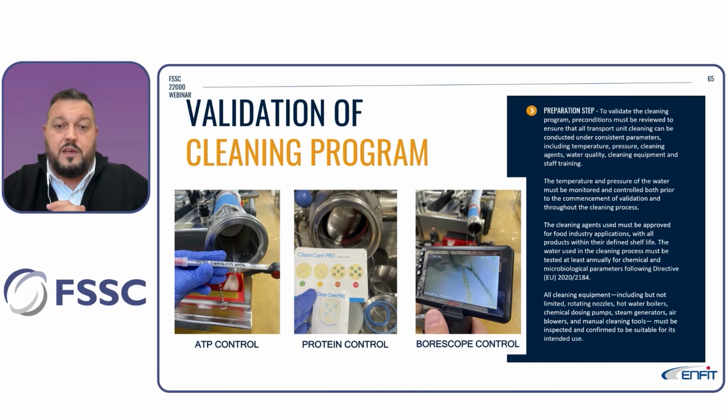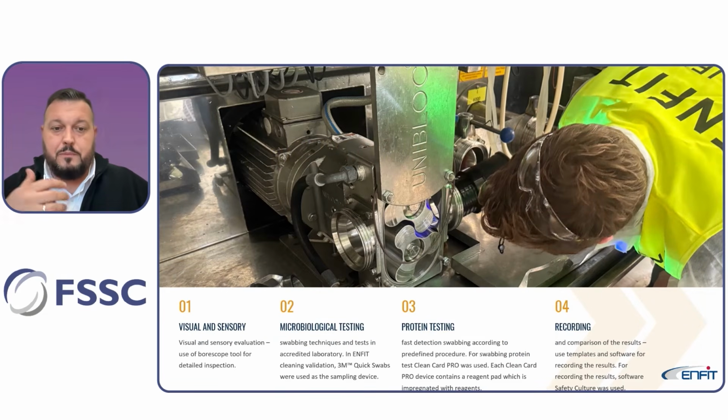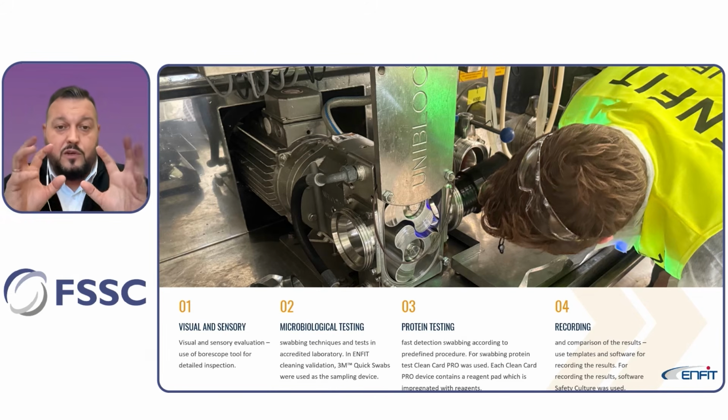That's why what we have done, we have developed the cleaning programs and also validated them. And we are giving also the structure for the validation of cleaning program. If we go to the next step, I will explain that starting from the preparation, it means that you need to have prepared conditions. This means that equipment works well, that your controlling equipment works well, that you have defined cleaning programs, that you have checked the temperatures, the pressures, and everything works well. So you have preparation conditions.